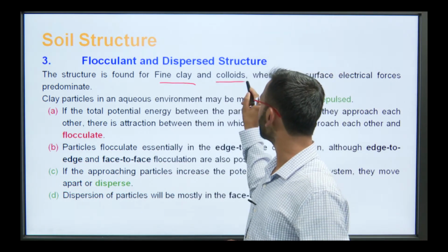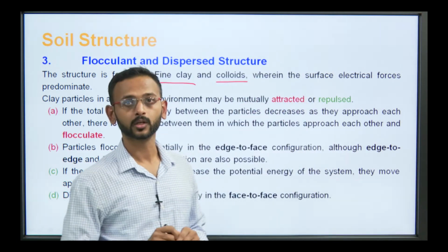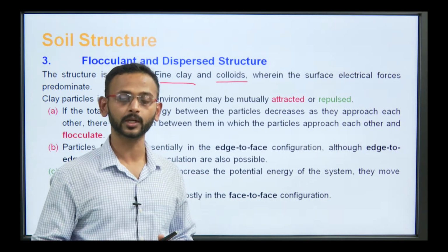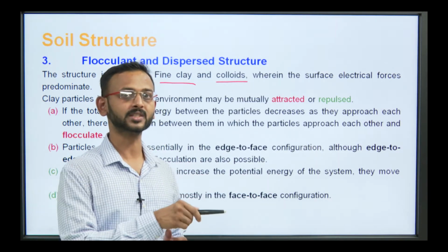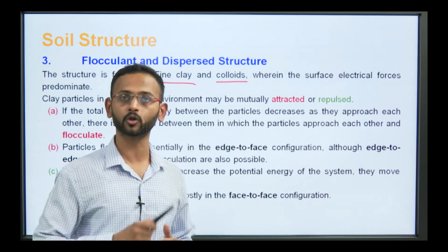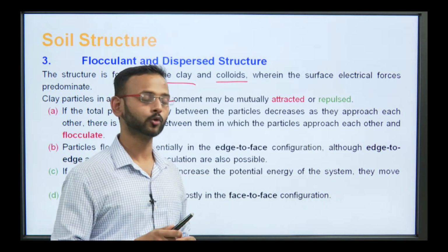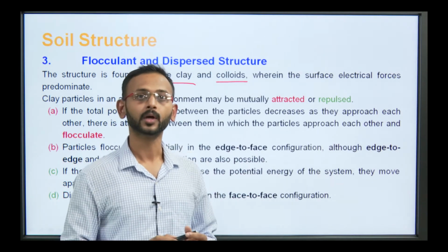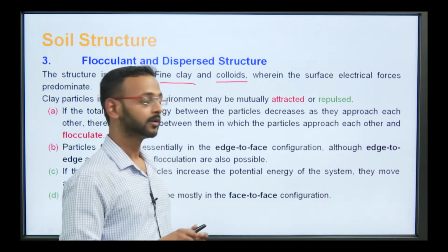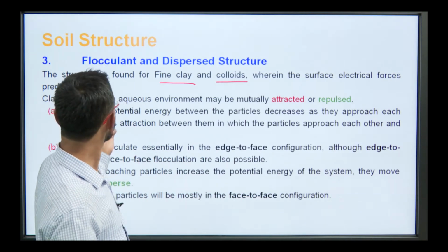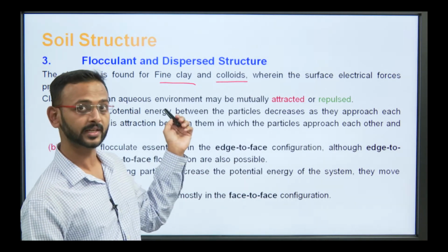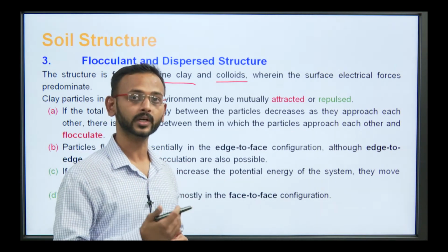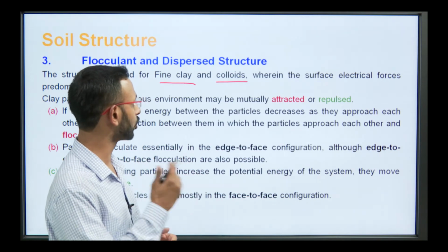So, fine clay and colloids. The very first thing we discussed was about the gravitational force being the dominant one. Now, the second one, the honeycomb structure, we discussed that it was due to the surface electrical forces and gravitational forces both. Now, here in the third one, the particles are finer and the surface electrical forces are dominating over the gravitational forces, that is, they are more.